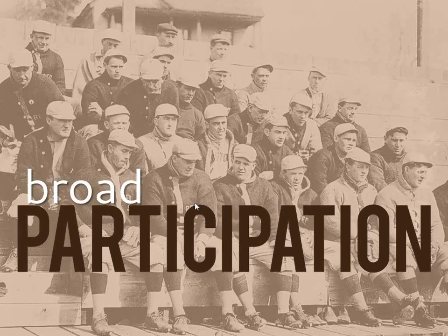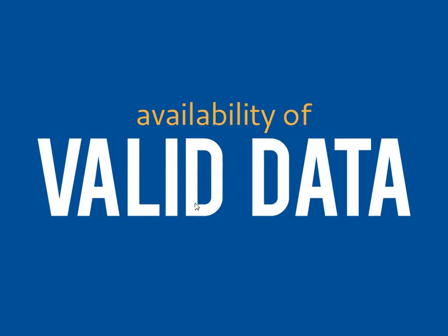The second characteristic is to have broad participation in the preparation phase of the project. We want to make sure that all the stakeholders are being included. That could be government agencies, the community, project managers, estimators, and the planners. Everybody needs to give their input and together come up with a mission of the project and be detailed about the requirements of the project's parameters. We also need to have the project's requirements reviewed independently so we can verify and confirm that the plan we are starting with is complete and reliable.